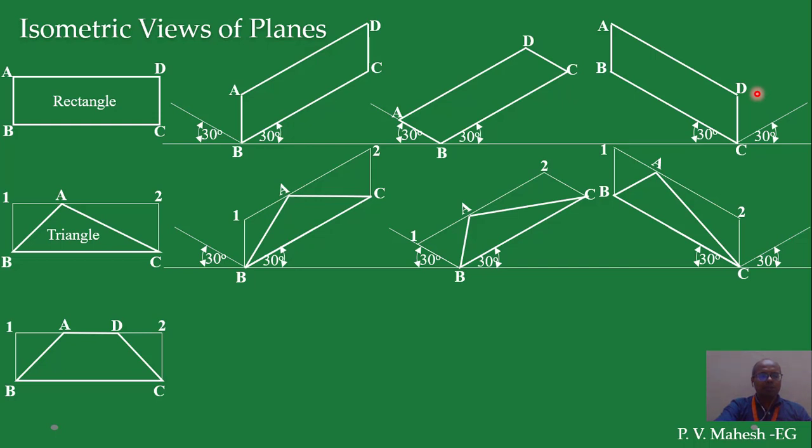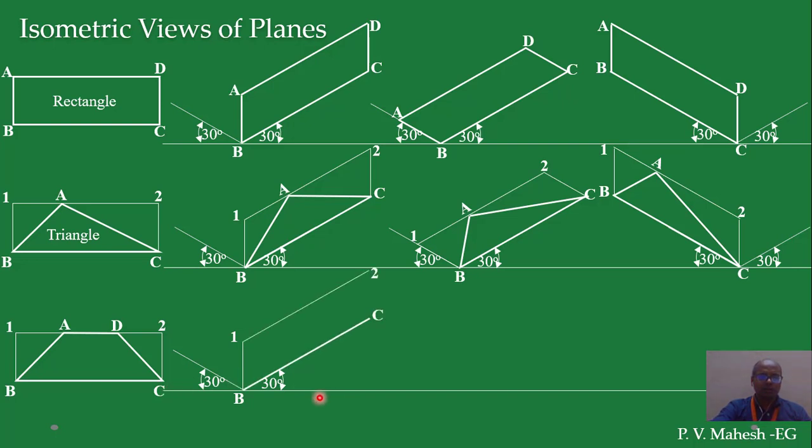So this is the trapezium, and it is enclosed because these two have some oblique angle. We enclose it inside the box, and first we draw the isometric view of the box. The isometric view of the box means B1 to C. B1 is a vertical line, and 1, 2 and BC are 30-degree lines from this side.